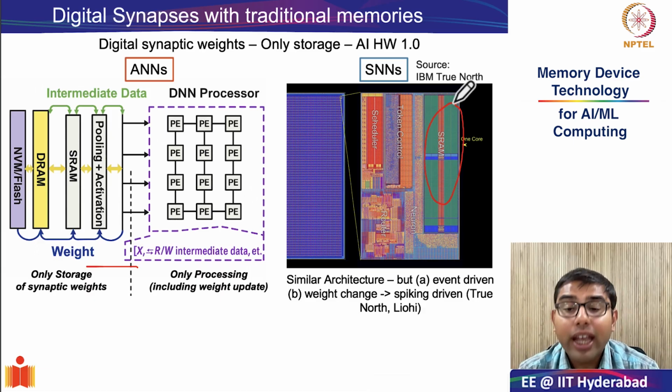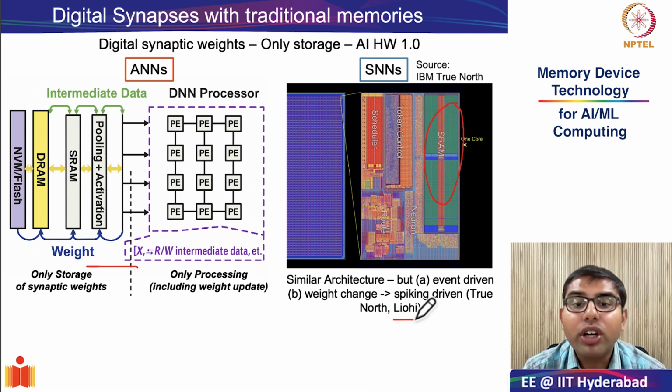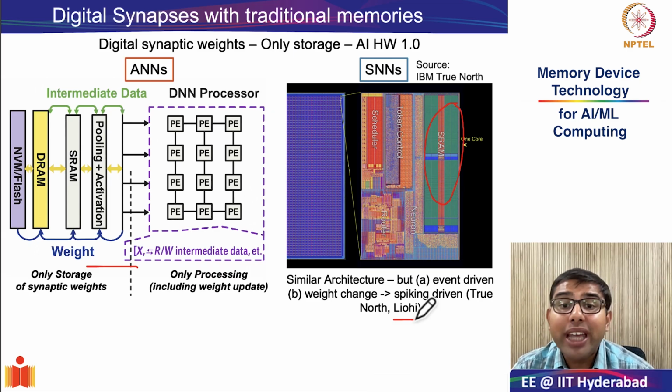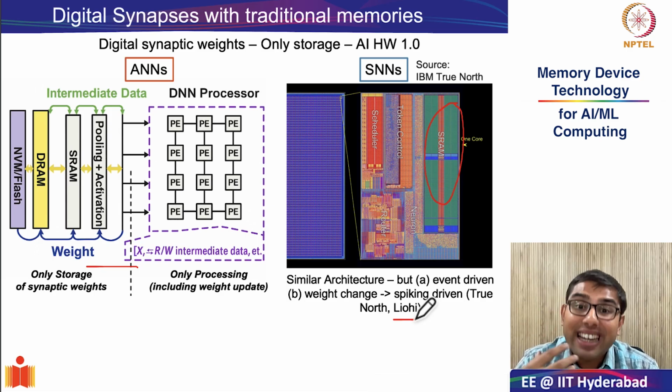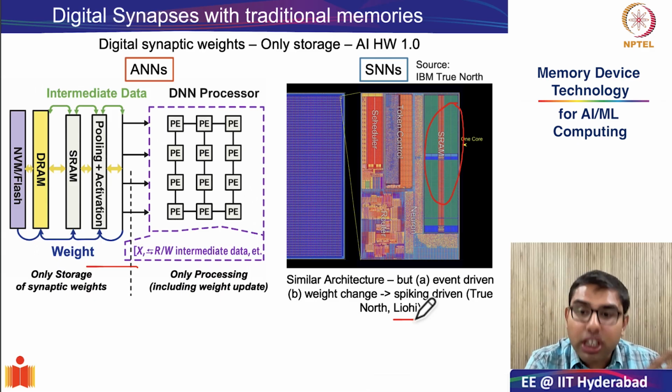In newer digital implementations that we will see later in our course, such as Loihi, on-chip learning is possible, but it is still handled by some external supervisory logic or control circuit. What I mean is that the weight update is happening based on spike timing dependent plasticity, but this decision is not made by that nanoscale element or the synapse. It is made by some other digital logic.